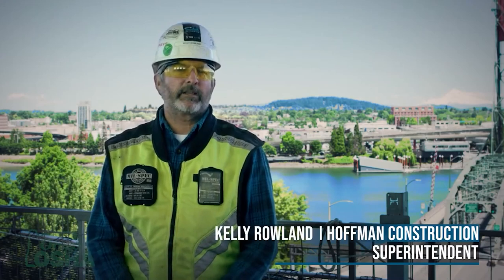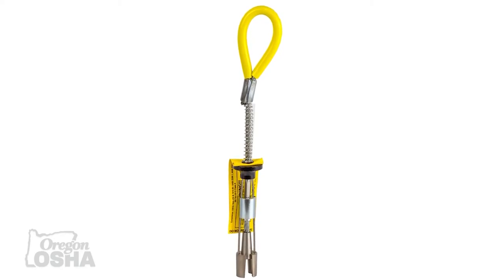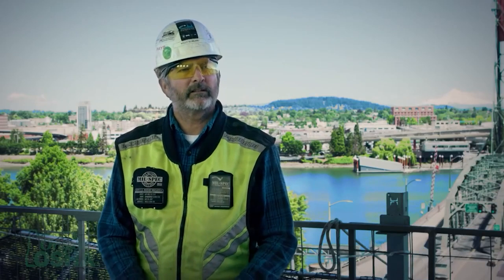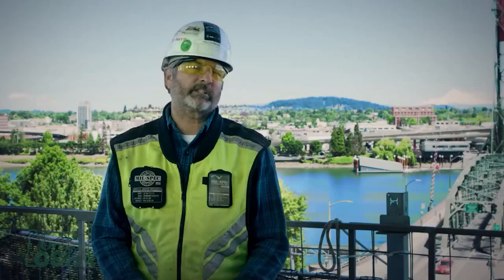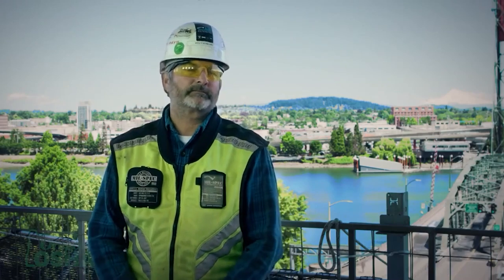The most popular type of anchor is going to be either a mechanical one, like a wedge anchor, where you drill a hole and then there's a mechanical way for it to tighten up. It has engineering behind it. My favorite is cast-in anchors. Not only do you have the anchor and the pull-out of the threads of the bolt that you're using, but you have all the concrete there as well.